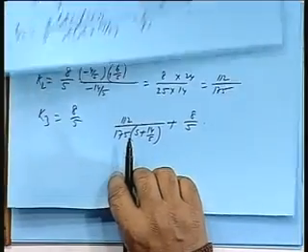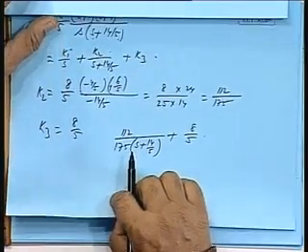So, from Z2 what should you do? From Z2, what do you do? Again go back to Y2, then again weaken a pole so as to realize the other 0, that is at minus half. So, you have to remove partly one of the poles so that the 0 shifts to minus half. Again realize it by taking a factor 1 by S plus half, by inverting it and making the partial fraction.